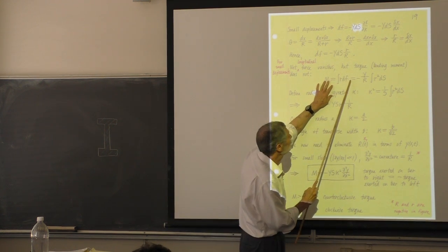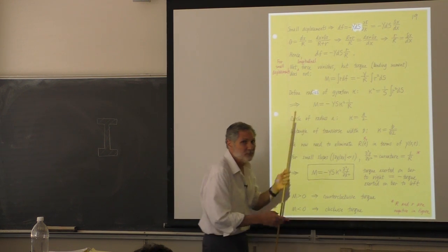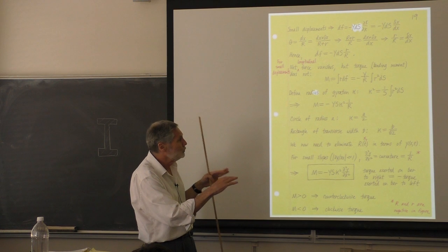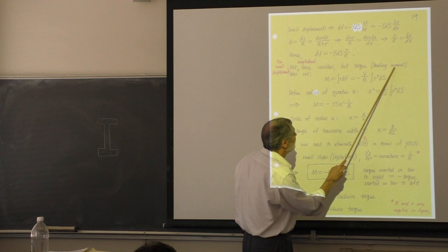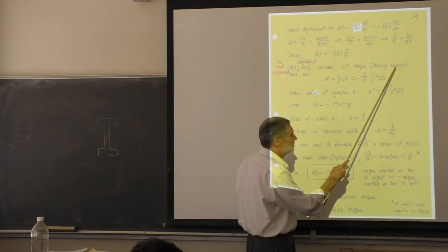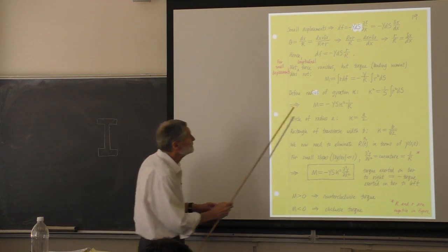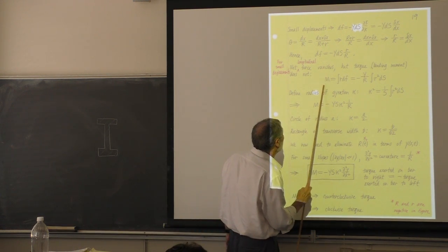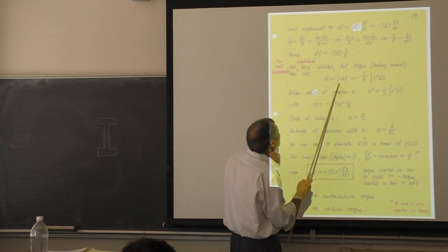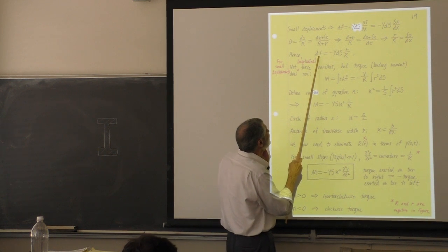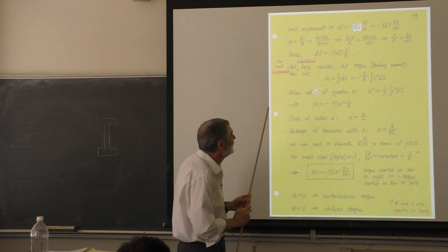Force times distance. So our little filament here is exerting a force dF given by that. It's some distance from the neutral plane, so it contributes this amount to the torque. The word moment here signifies force at a distance. So a bending moment is the same as a torque. So here's the torque, and we use M, probably for moment, but I don't know. We need to do this integral here. We take the force here from the filament, put it into here, and then we integrate over all filaments.